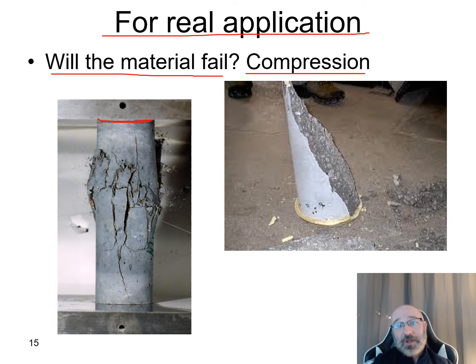And this is a case where it's not necessarily compression or tension, and we can actually get that information from some of these tests. And we've seen some ways that we've done tension testing on concrete where we've actually put a rebar into this and pulled on either end. So we want to see how it reacts in both compression and tension.